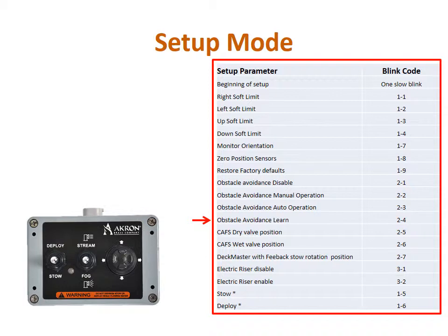Starting with the monitor in either the lower left or lower right limit of travel, slowly move the monitor toward the opposite side. When you come to an obstacle you wish to avoid, stop traversing horizontally, then move the monitor up, across, and back down to the desired level on the other side of the obstacle. Then continue toward the opposite side. Continue this process for any other obstacles along the way.